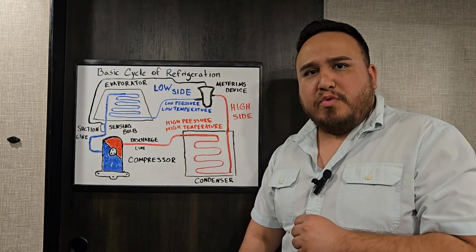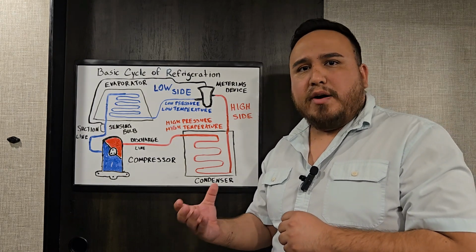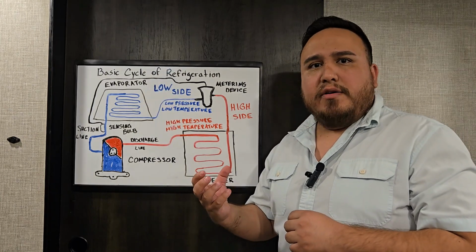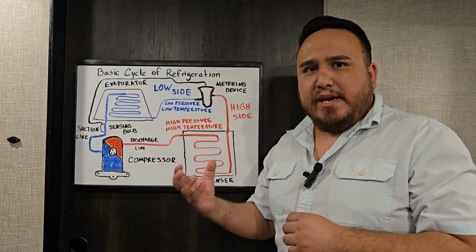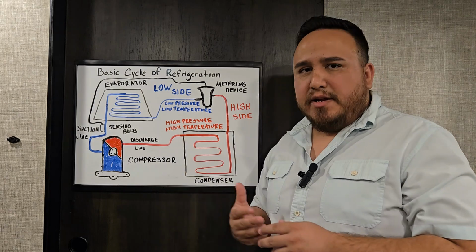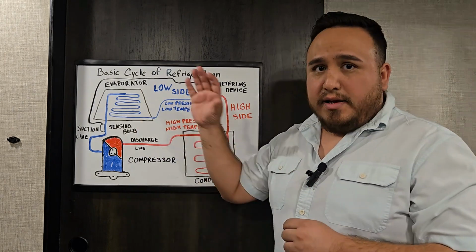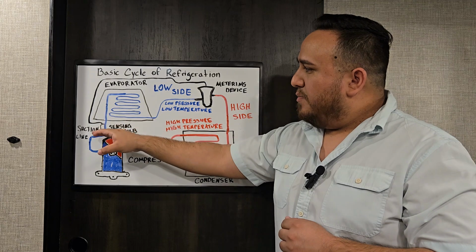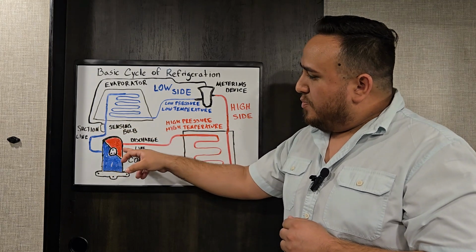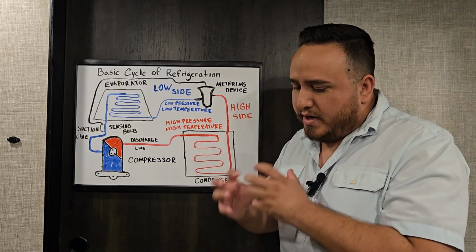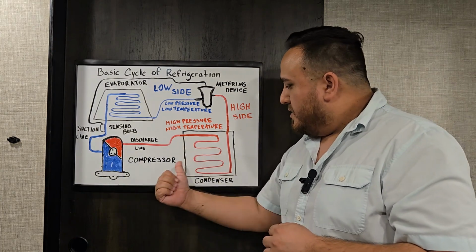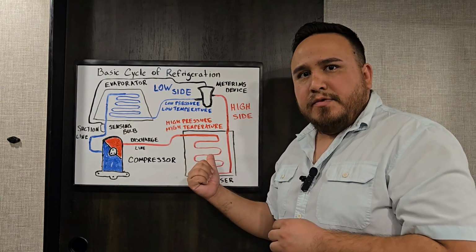You dip it in that bucket of water, it's going to go ahead and absorb all that water, all right? So the same thing, the refrigerant is just absorbing all that heat. And where is it taking it to? Well, now that heat is transferred. In this case, it's going to be sent all the way into my compressor. My compressor, once again, is going to continue compressing that refrigerant. It's going to shoot it out, and it's going to go into my condenser.